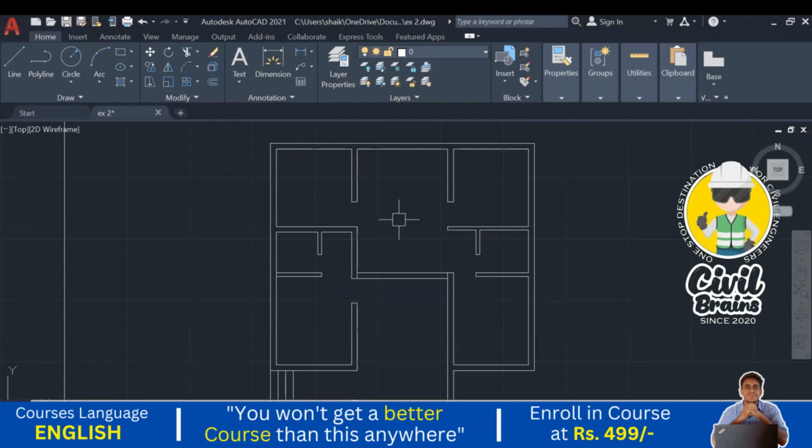Next, whatever wall we are going to provide the windows on, we provide them at the center of the wall. Why at the center of the wall? If we provide it at the center of the wall, it is for better circulation of the air and for better sunlight, and from the aesthetic point of view also it will look good. Depending upon the types of windows and the design of the building it can change, but in most cases, for better ventilation and better sunlight, we are providing the windows at the center.